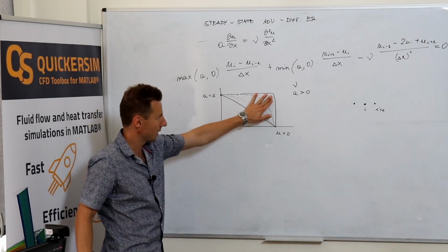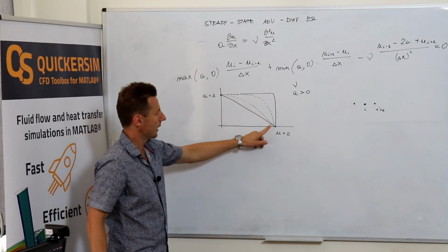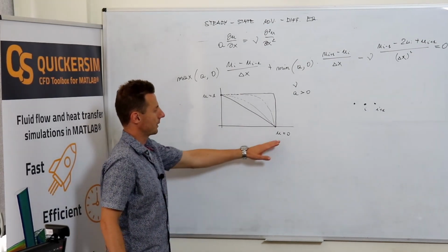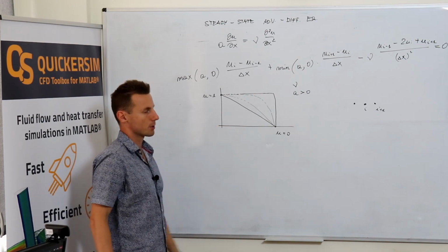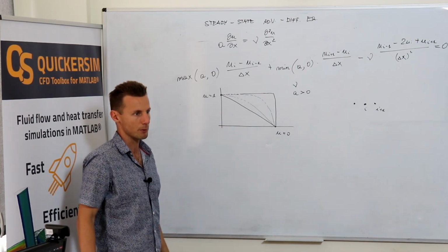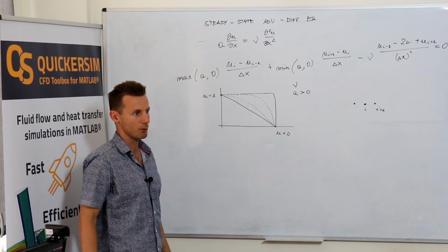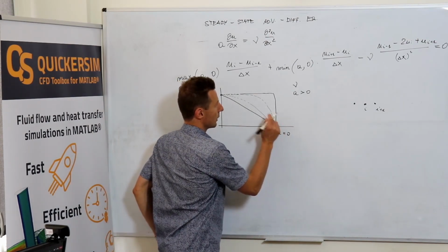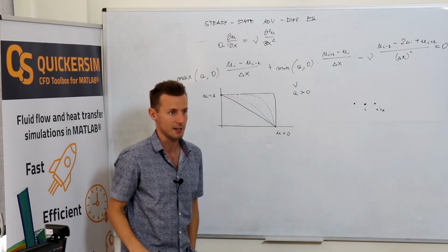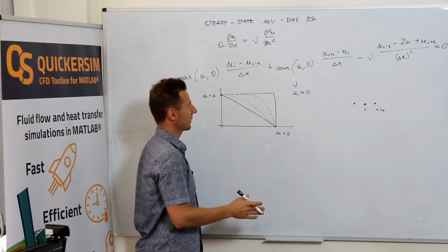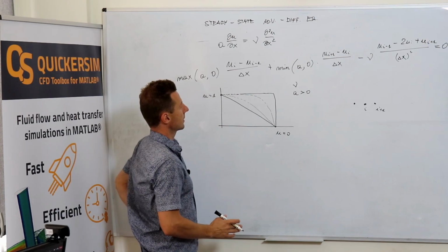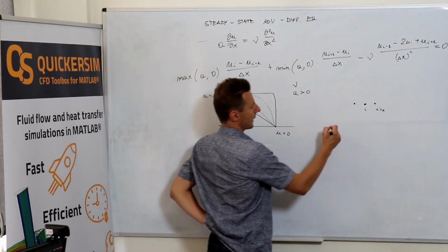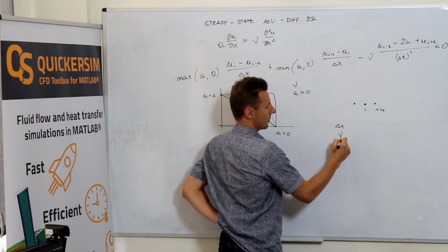And I think it's extremely worth doing because it's the simplest way of seeing what can happen in numerical procedures if you need to resolve steep gradients, for a boundary layer, for example, or steep gradients in heat transfer. This means the advection diffusion equation in the steady state is a perfect illustration of what can happen. And what you would see, especially playing with delta x, diffusivity